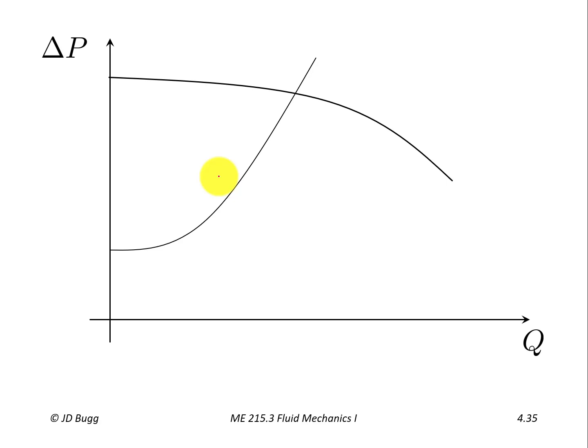So if we go back to our system curve equation, there's a Km in there. One of those Km's is the valve that we're talking about. We open the valve, that value of Km decreases. So we're decreasing the variable system pressure, or we're decreasing the value of B. So what would happen is this parabola would not rise as quickly. So by decreasing that K value, by opening up the valve, our new system curve would perhaps look like that.